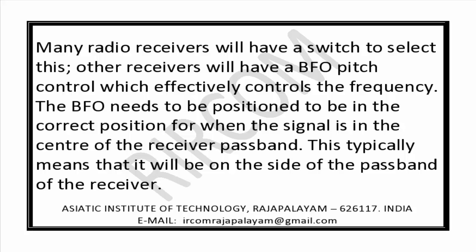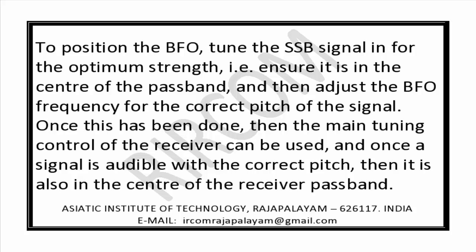The BFO needs to be positioned to be in the correct position for when the signal is in the center of the receiver passband. This typically means that it will be on the side of the passband of the receiver. Tune the SSB signal in for the optimum strength, that is ensure it is in the center of the passband, and then adjust the BFO frequency for the correct pitch of the signal.